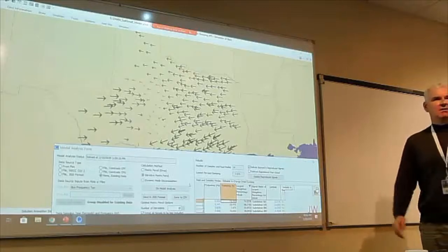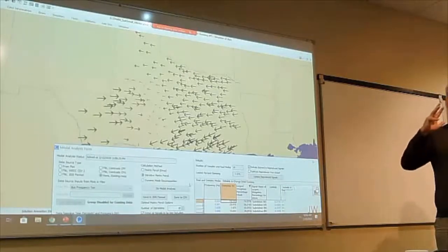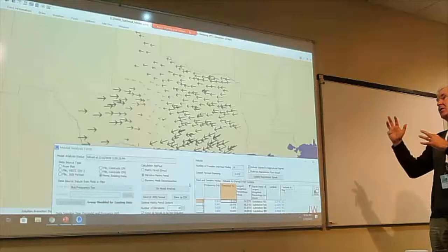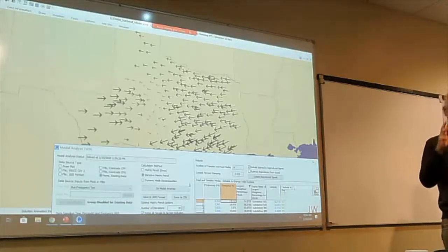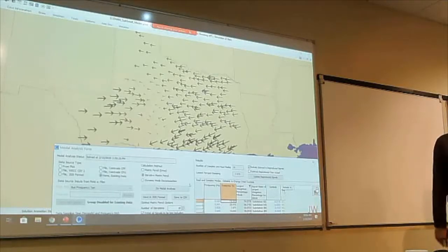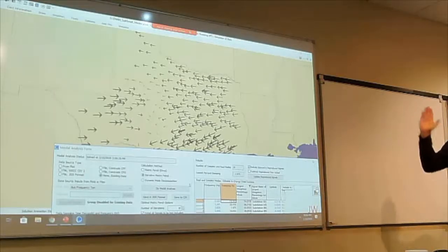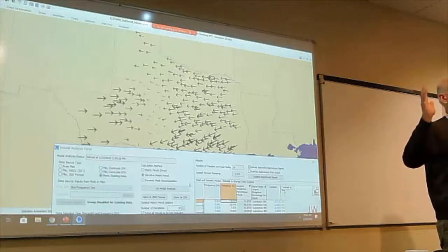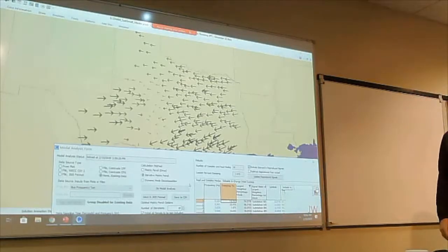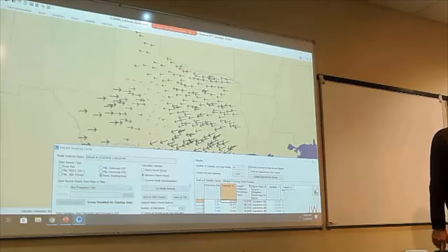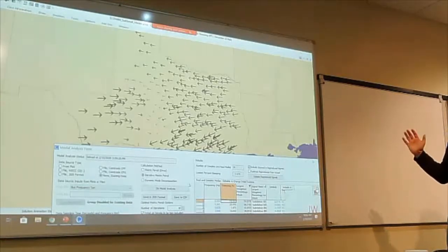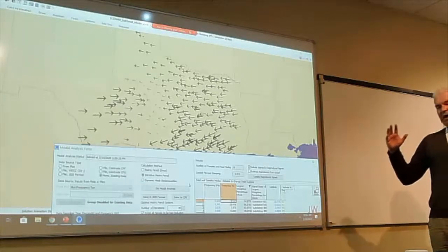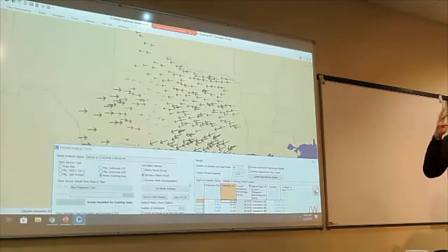You see that. And in WECC you guys have modes. The East doesn't understand their modes as well as the West, but we can take an Eastern Interconnect case, run it, and show all their modes. It's more data, because if we ran all the substations in the East, it'd be like 50,000 or 60,000 substations. But we can do that and start visualizing them. We're going to do a project for SPP where we're combining the West and the East, and we're going to run it all together and see what happens.